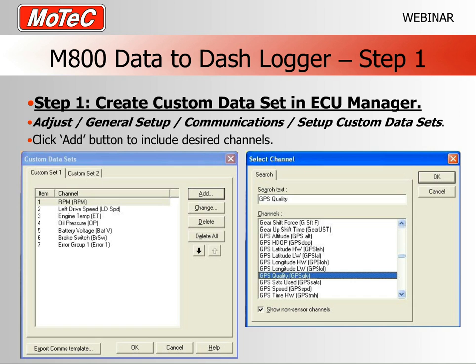I've just selected GPS quality here. Once you have the channel that you need to add, you click on the OK button, and that will then appear on the list on the left hand side. So it would come down here as number 8 entry, and you can continue to add extra channels until you have the custom data that you need.